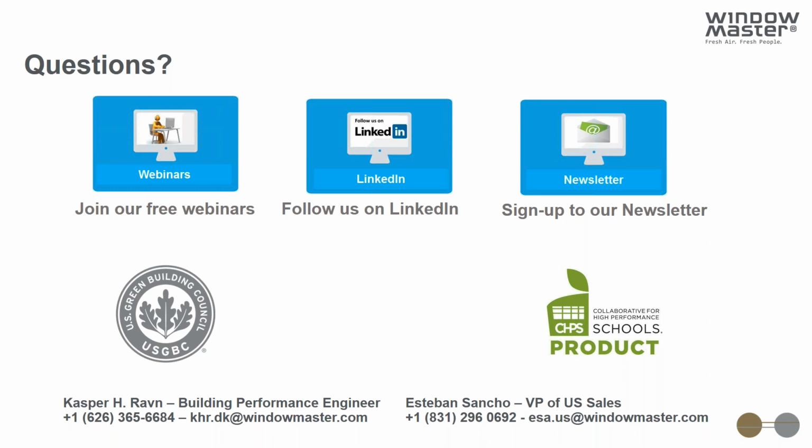Yeah, of course. And that's also one of the hard things in the wintertime with the pulsing strategies. That's also to avoid major heat losses. It's both avoiding draft problems, but also, you are implementing natural ventilation to save energy. So you don't want to turn off the radiant system and then open the windows 30 degrees and let it all out. So of course the synergy between the systems is very important,